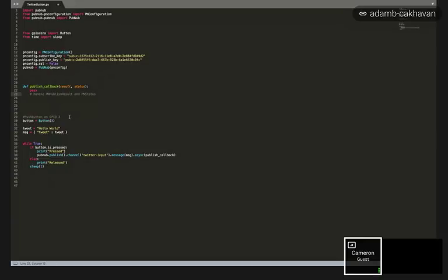So the important thing here to note is use the GPIO Zero library to make a button. And this is actually the beautiful thing about the GPIO Zero library, that all you have to do to hook up a button is just type in button and then your GPIO pin number, like I said before, and save it to a variable. And the reason why you may not realize this is so special is because you don't have to worry about anything that a hardware electronics engineer would have to worry about, such as debouncing.